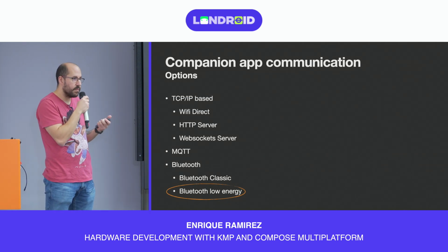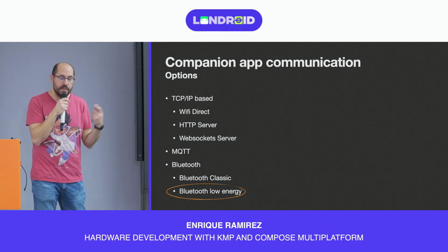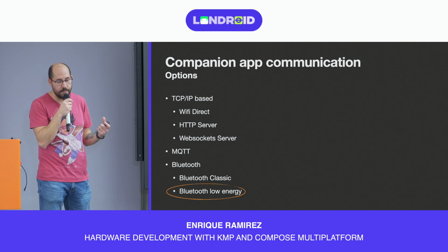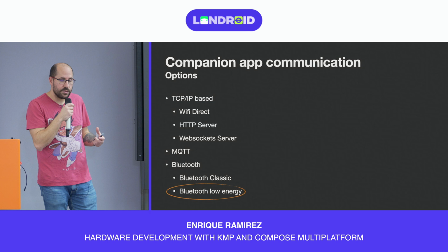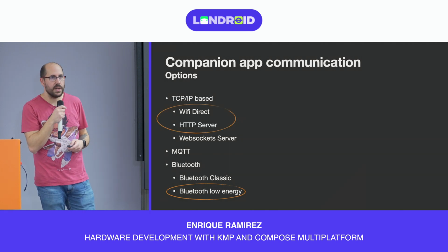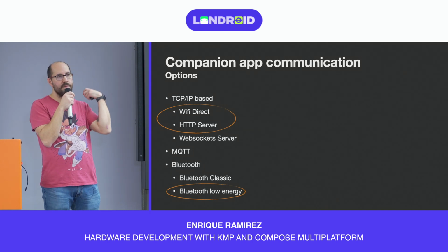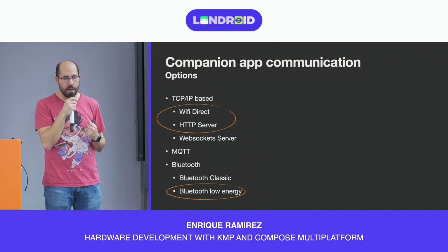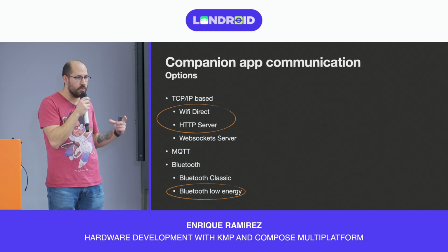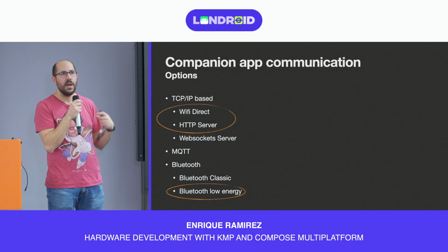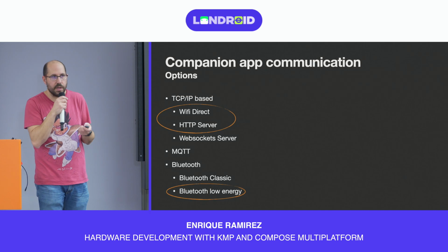It also has very low power consumption, but the only problem it has is the messaging: the payload that you put in Bluetooth Low Energy has to be very little. That's a constraint it has. But I also thought, if I want to take this even further, I want to get to a point where I could connect an app and send a custom image to show on the screen of the pedals. And for that, I will need something like Wi-Fi and HTTP communication.